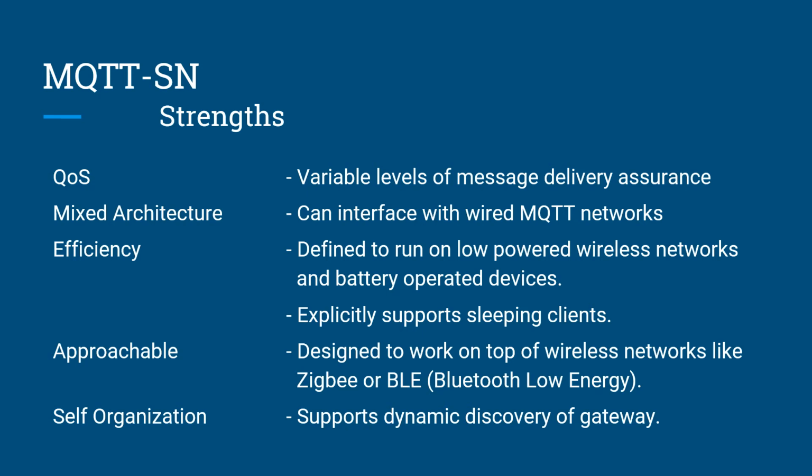It's designed specifically for efficiency to run on low-powered wireless networks and battery-operated devices, and it explicitly supports sleeping clients. It's approachable in that it's easy to implement, and it's designed specifically to work on top of wireless networks like Zigbee or Bluetooth Low Energy. And to some degree, a small degree I would say, it supports dynamic discovery of gateways, which allows it to be somewhat self-organizing.